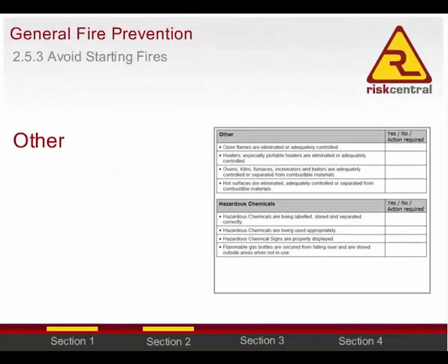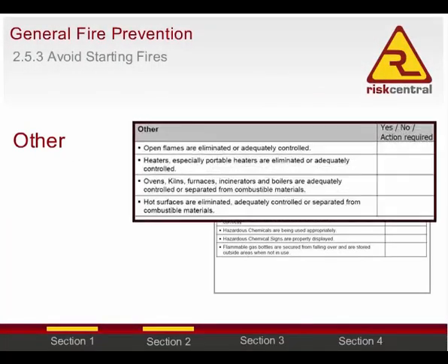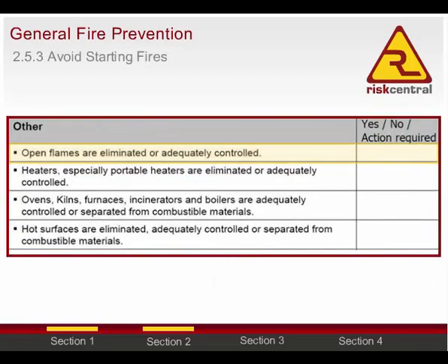Other. Open flames are eliminated or adequately controlled. Heaters, especially portable heaters, are eliminated or adequately controlled. Ovens, kilns, furnaces, incinerators and boilers are adequately controlled or separated from combustible materials.